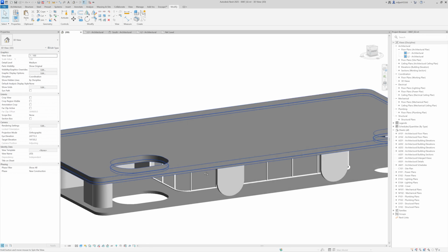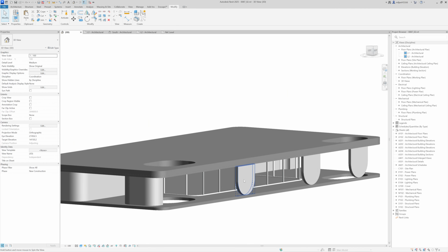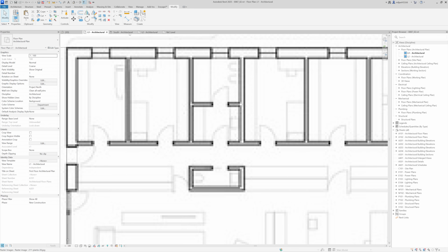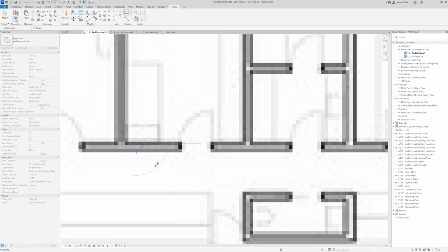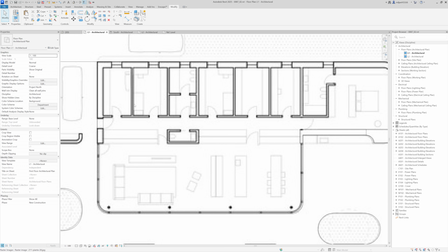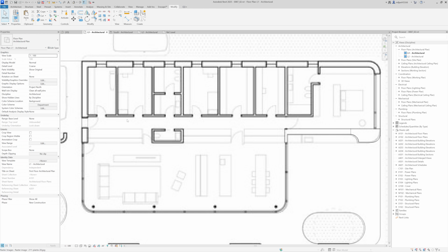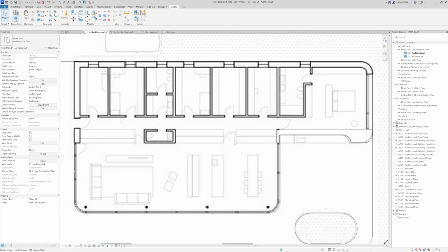So the house gets shaped. Okay, and now what I'm gonna do is to create those interior walls. So they have a thickness of around 200. I'm going to place them randomly, approximately actually, and then using temporary dimensions, I'm going to position them very precisely.